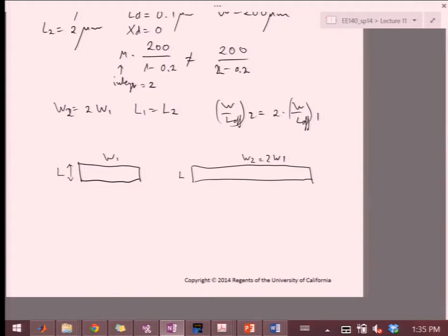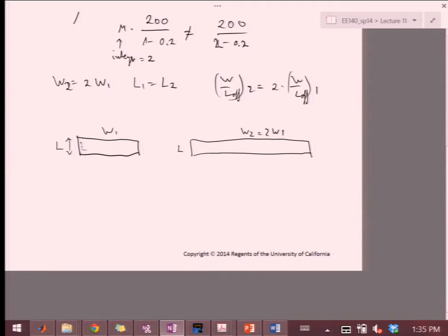The way lithography happens, you actually have the active area underneath that is also shrunk from the W side, because of the edge effects of forming the channel in the fields.